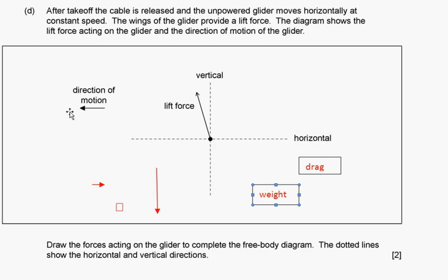The direction of lift has meaning, as does its magnitude. Another force is weight, and the drag force. Weight is downward, vertical. The direction of motion is important because the drag force is opposite to the direction of the motion. And here we put 90 degrees. So this is a closed triangle.